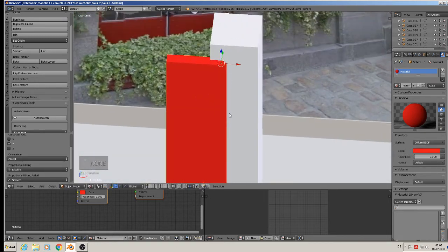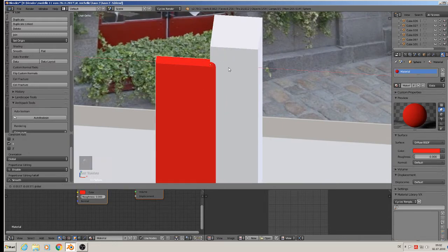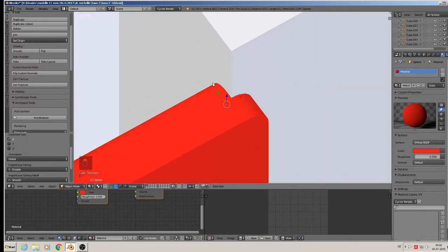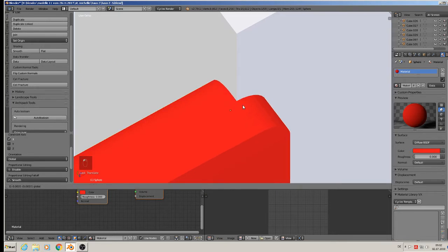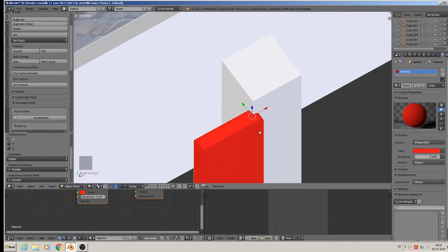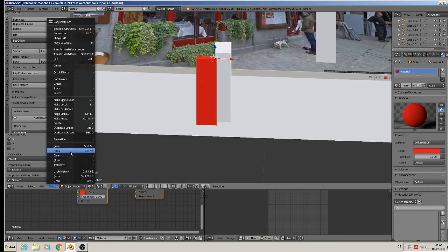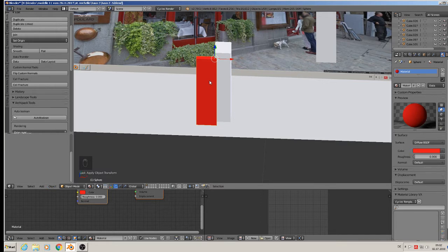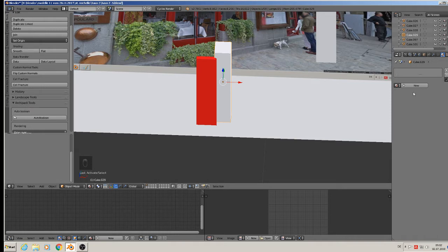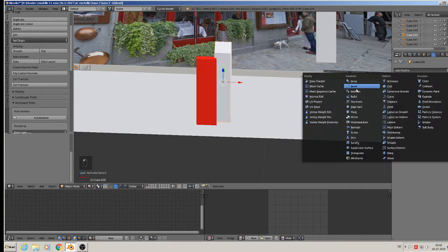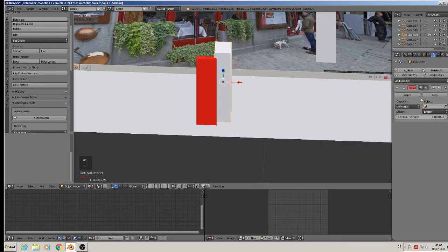And then here to the start of the roundness there, so that it can cut the round part out. Good. We object apply the rotation scale again. The name of the object is sphere. So we go here to our base mesh there and say we take a boolean. We want to difference the sphere. So we have them there and say apply.